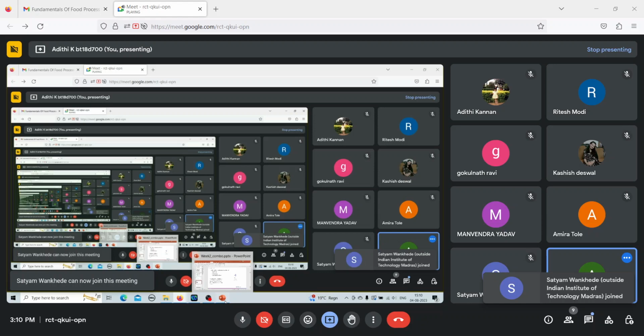Here you have the Kelvin model, the spring and dashpot connected in parallel, and then a spring and dashpot connected in series. So this is the Kelvin model, this is the Maxwell model. Together this is known as the Burger model that combines both. So the answer here, as you said, is option C. Hope this is clear. Different kinds of models.